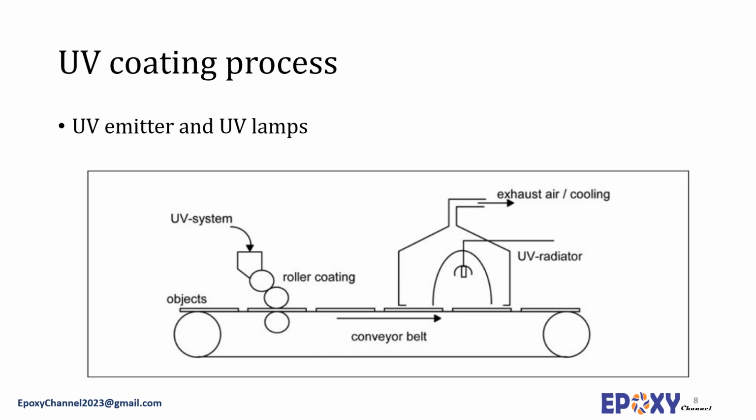The choice of UV lamp depends on the application, whereas the UV curing is influenced by the radiation energy, light spectrum, and exposure time. These sources often produce a certain degree of infrared radiation as heat, which is beneficial for the annealing of the cured coating, relieving internal stresses and strains, or enhancing the cure rate in cationic cure systems.